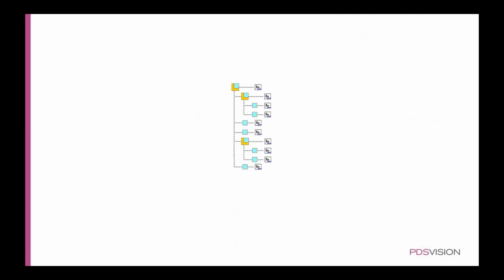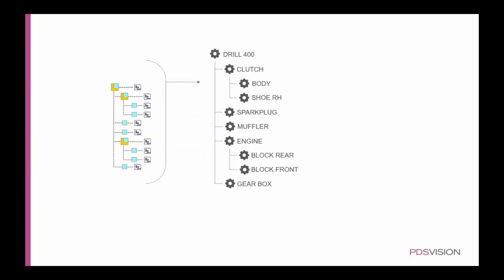So typically what we see when we first start using Windchill is these users already have CAD data, so we can instantly start leveraging the CAD data to derive a structured list. As I showed in my initial animation, when we checked in some objects, we derived a part from that. We can do the same with these whole structures. So you can see we end up with a like-for-like representation of our CAD structure. We can use this as a starting point. However, these structures can be created manually, or we can import them as well as exporting them. But that gives us a starting point.